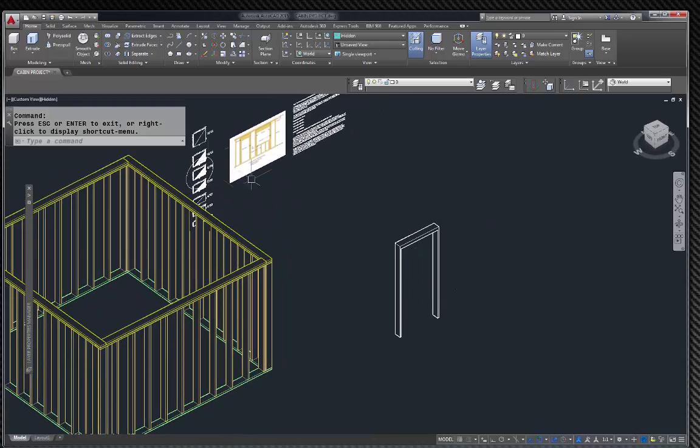Now I'm going to go up here, and I'm going to go to box again, and I'm going to pick up, and I'm going to go L for length always. Enter. Now, and F8. Now this wants to be 36. Okay. Enter. And this wants to be 2 for the width of the door. And this wants to be 80 for the height.